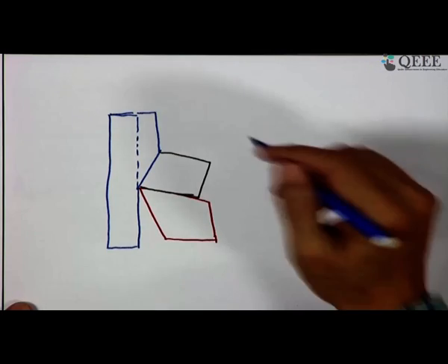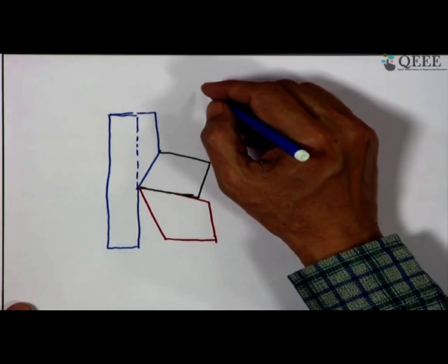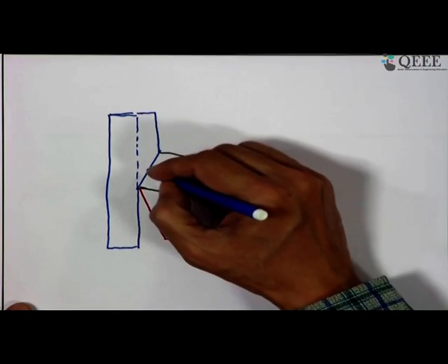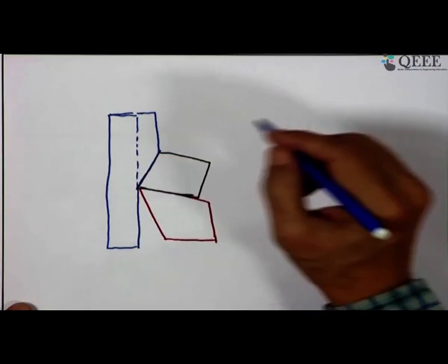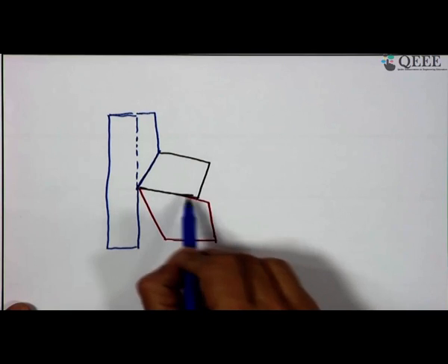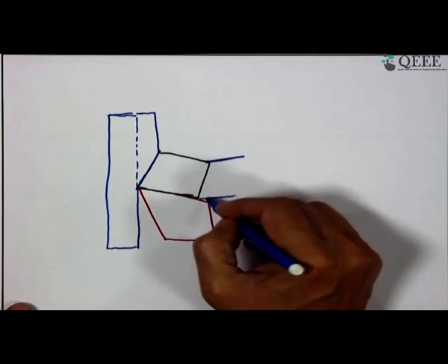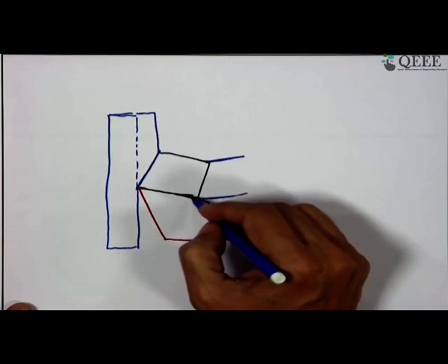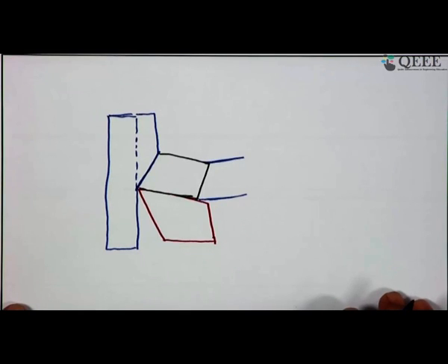So, here as we have said, you have primary shear zone, and then we have a secondary shear zone, that means primary shear zone, that means this slot from this is the primary shear zone, and then chip tool interface. After that it gets lifted. Okay. So, it gets lifted. So, it loses contact. So, up to this point this is what we call chip tool interface.